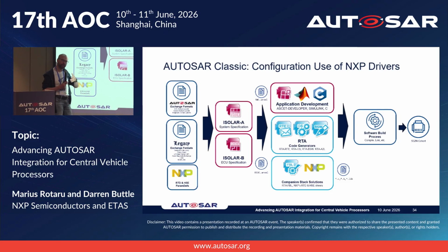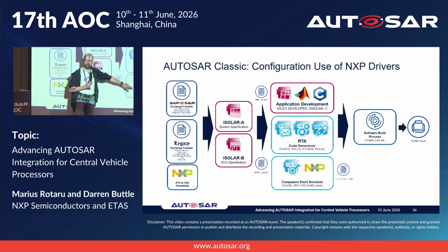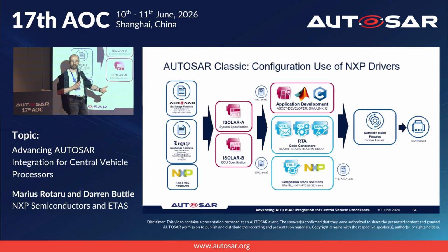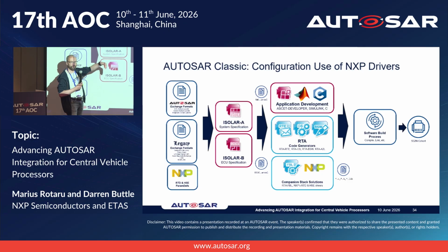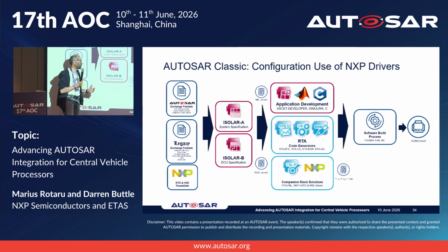So it's, for example, with the different crypto accelerators, it's taking each of those individual crypto drivers where we've got multiple ones being provided down here on the MCAL level, and it's binding those in using the normal AUTOSAR CryIF distribution thing. Say, okay, this is the crypto job I'm getting from the top of the CSM stack, configuring the CryIF, and then routing that to the appropriate crypto accelerator that's provided by the underlying hardware.